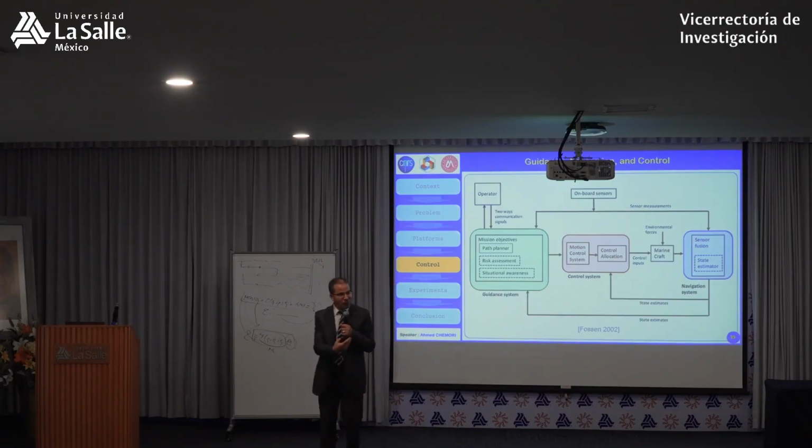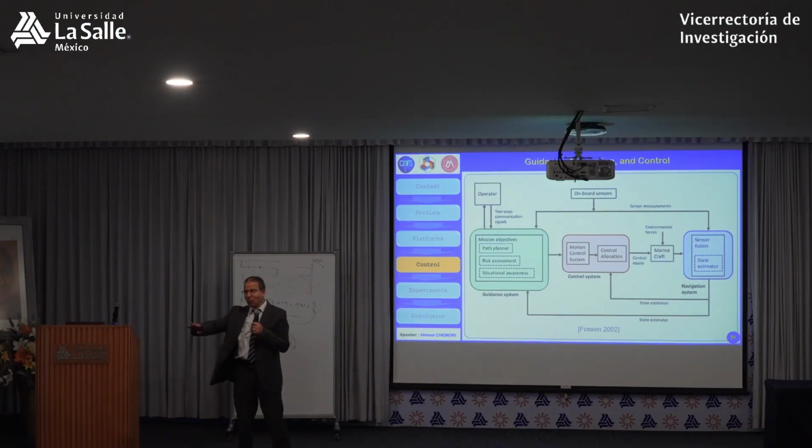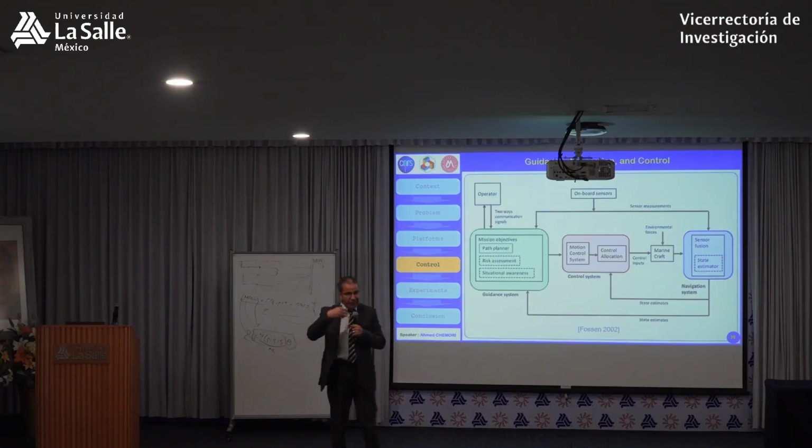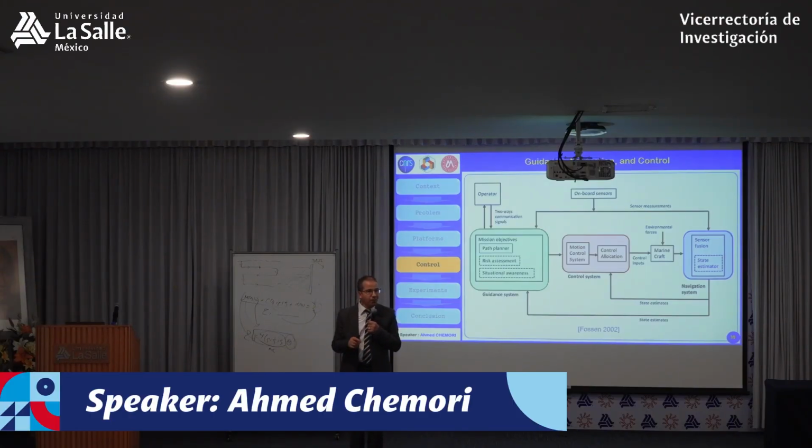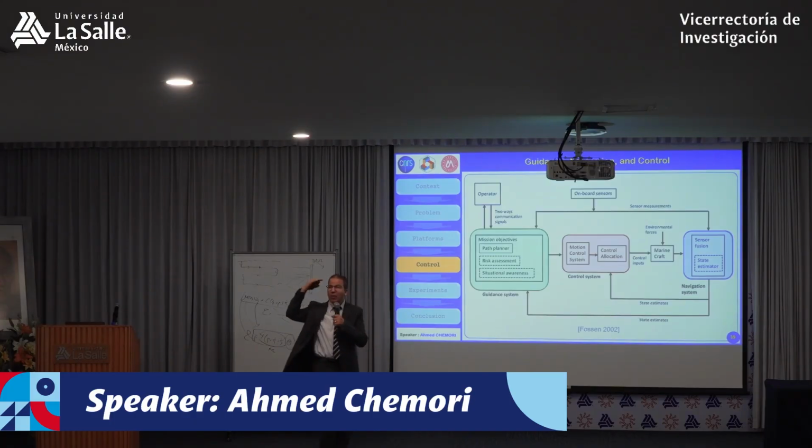Then you will be adrift because of currents, so the boat will move. If you want to stay at exactly the position where you are, we call this DP, dynamic positioning. You try to use the propellers, the actuators of the boat, such that you stay there. This is called DP, and the desired value is a constant value of this position. So here, you try to control something where you have a constant desired position.